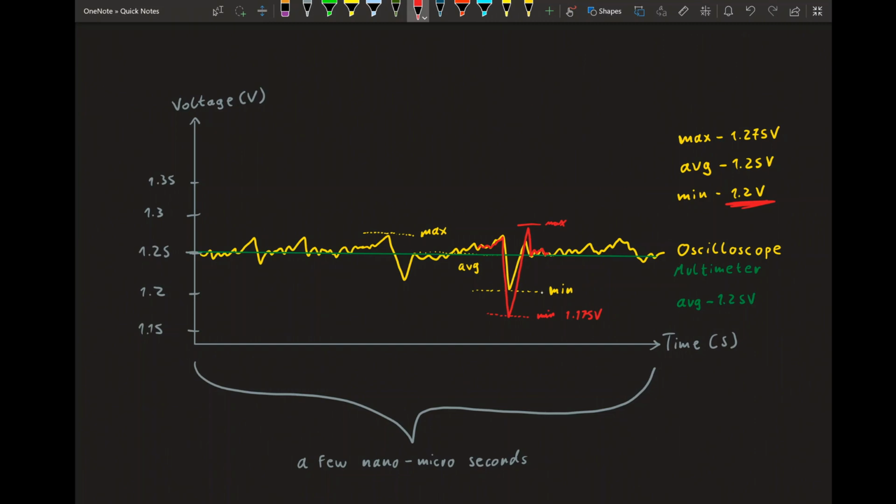Because the oscilloscope will show you a graph like this, it will give you measurements like your average, your minimums, it will even give you your maximums, those are way less important. And that's the important bit. That's what I will be measuring with the oscilloscope, and I hope I can get a few good examples and show you what's happening, because really an oscilloscope is the only piece of equipment that can actually visually show you how your VRM is performing or how mods you're doing to the VRM are affecting it, outside of just, oh, my thing runs a higher clock now after I did those mods.